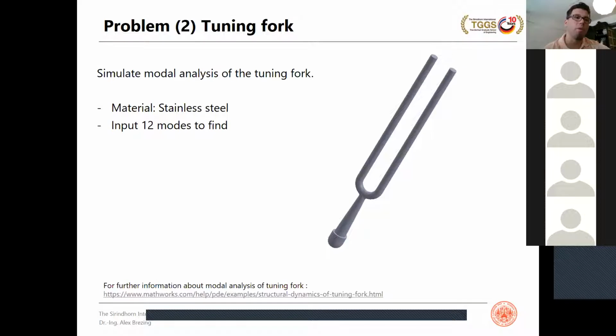So our modal analysis should give us a specific frequency for this model, and I've already given you on the shared drive the Creo model for the assignment, and I've also given you, I think, a STEP version of that same geometry. So you will be able to use that for the first run of the analysis. And again, the lowest mode that you can find, its frequency will be the frequency you can hear as a musical pitch.